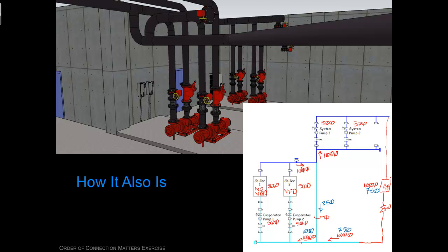In the first instant that happens, the chiller's running at full capacity, it sees its leaving water temperature start to drop, its control system backs its inlet vanes off, and it unloads the chiller to match that entering water temperature and the capacity required to maintain it. And so the chillers unload. We're at part load, the chillers are unloaded, all is well with the world.